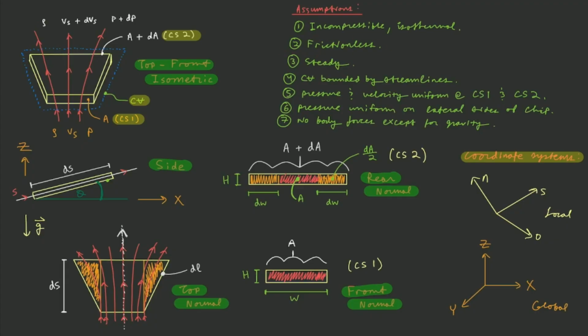2, we're going to assume that we have a frictionless flow. That's incredibly important. And this is typically where Bernoulli's equation is misapplied. If you apply Bernoulli's equation to a system with a significant degree of friction, so perhaps a system with a very low Reynolds number or with a lot of entropic losses, Bernoulli's equation will give you the wrong answer. So you can only apply it to systems that are reasonably frictionless, and we'll get into what that means.